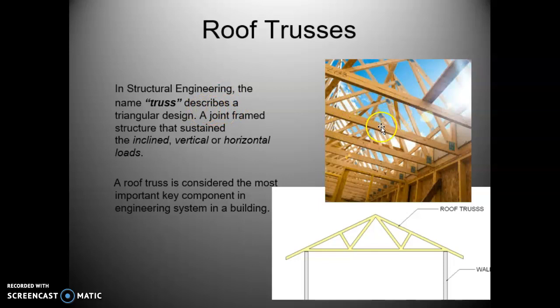99.9% of the time, these trusses are made off-site. The great news about that aspect of it is you can order your trusses right after you have your drawings put together. So, in other words, if you have your walls laid out and designed, I see your floor plan, we can start ordering your trusses directly off of that. Good news about that is I can start framing the house, putting up the walls before the trusses even show up on site. Time saver.